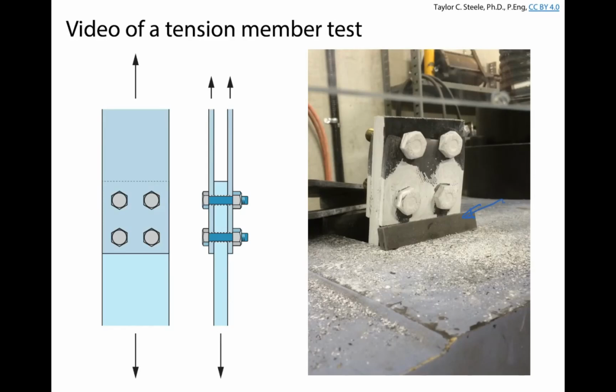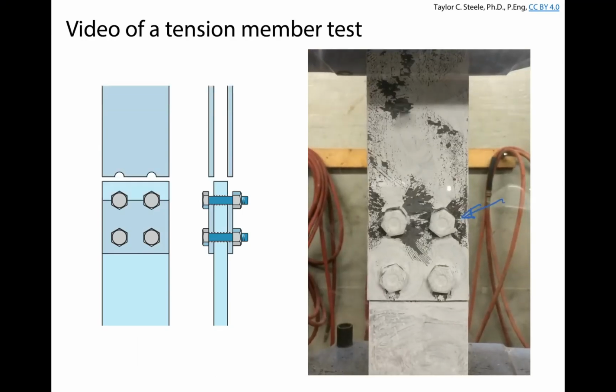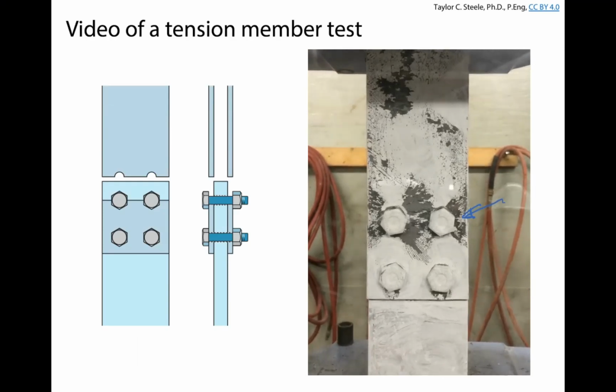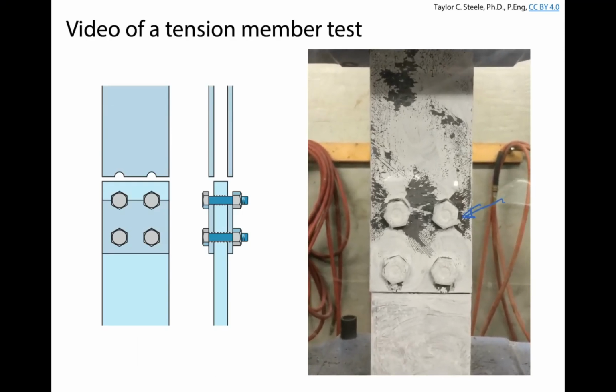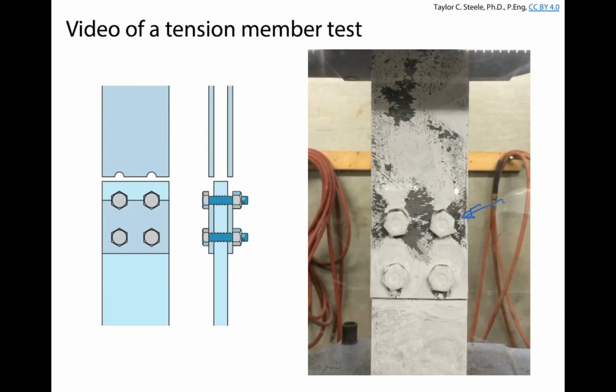And basically what happens is where the area is reduced because we're poking bolt holes into this cross section to make sure that we can fit it together with bolts. Basically the thing's going to get pulled apart, and I don't know why it's showing you there again. Basically the part around the bolt holes gets separated across, and this is what's referred to as net section fracture.